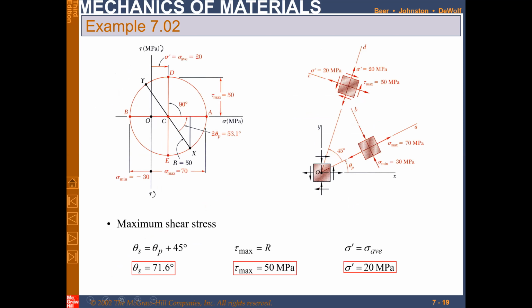And then you will further add 45 degrees, right? From theta p, from this point, this is the sigma max point, and tau max exists at 90 degrees to theta p, or 45 degrees in terms of theta. So this point will reach over here, and then you will go another 45 degrees from this point.